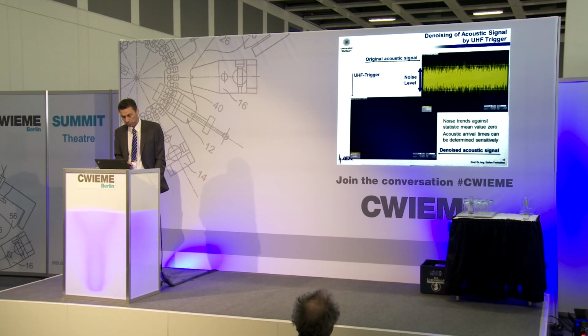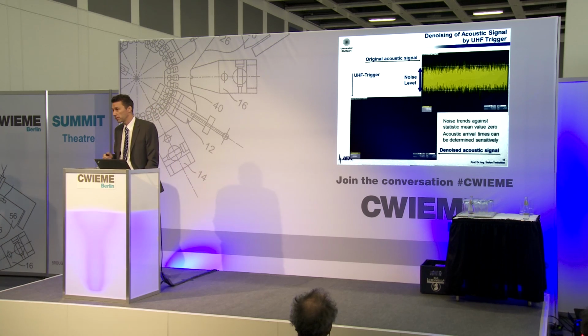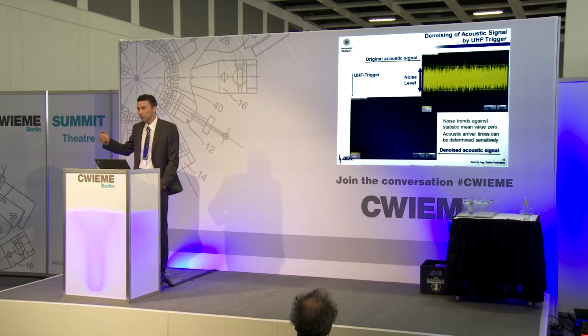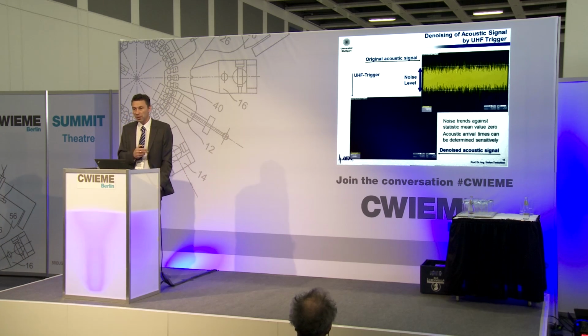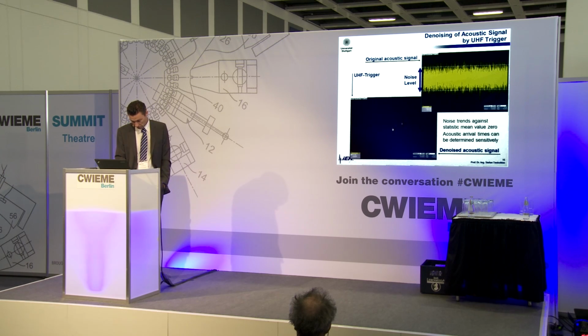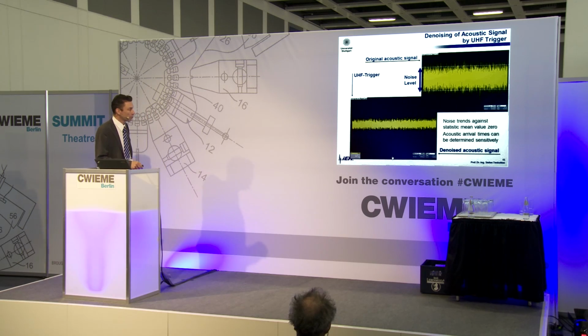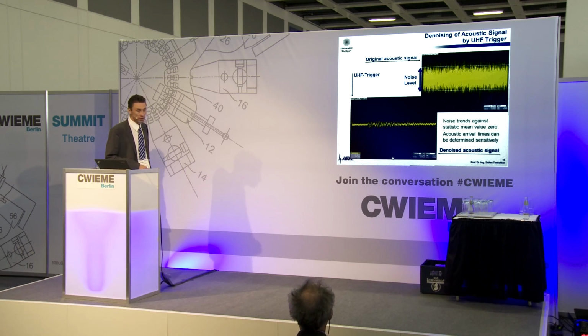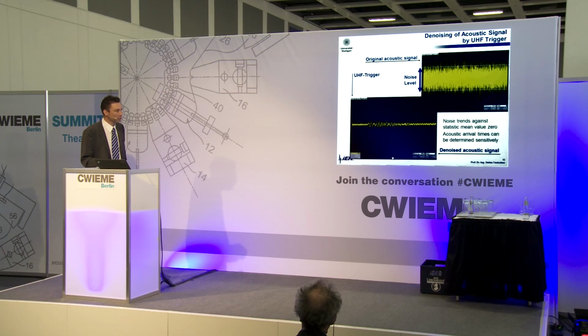from the acoustic sensors. And if you now look at this signal, you would say, okay, this is simply noise. What can I read from this signal? But if you measure a lot of these acoustic signals and calculate an average signal, you can decrease the noise level. Because the noise is of course statistically distributed, and if you build an average, you decrease the noise. This can be shown in the video which I show here. So we accumulated here 20, 30 and more of these signals, and the more you have, the lower the noise level is. And after a while, the real acoustic response from the microphones comes out of the noise.